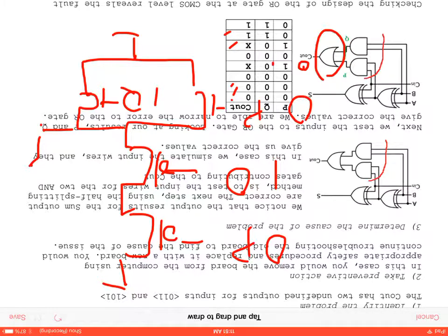So what's supposed to happen at 0 and 1 here? It's going to output a 1, and how's it outputting a 1? Which path? The PMOS. Well, it's supposed to output. There needs to be a path. So if it's outputting a 1, it would go through both of here when P and Q are both 0, right? Remember, this portion is a NOR gate, so it's going to be 1, 0, 0, 0. So it has to be 0, 0 in order to output a 1. So it should output a 0, but it's outputting an indeterminate value.